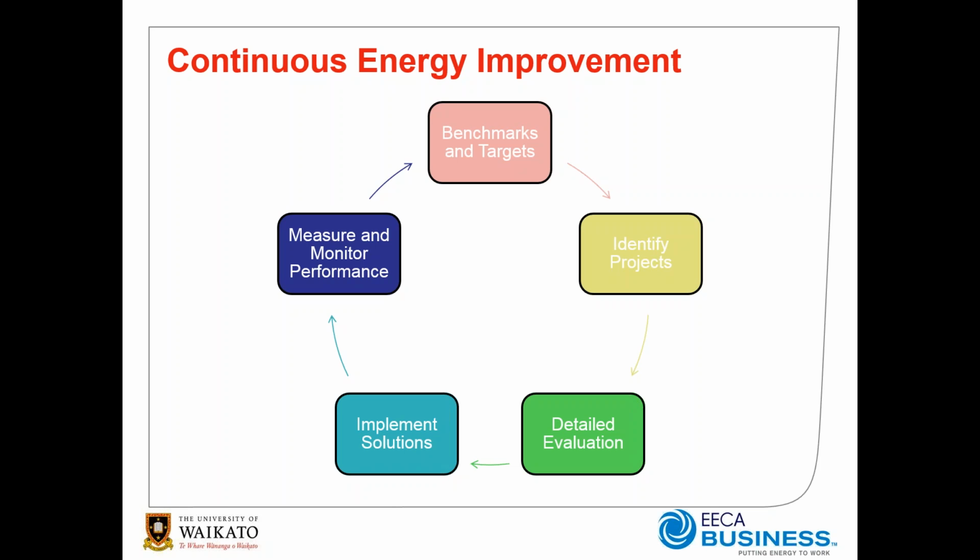It may also include a process simulation of the changes in order to predict what the energy benefits are going to be, as opposed to just an approximation. And then thirdly, it may include some sort of systems optimization where you change both the process operations and the set points of your operations and also the heat exchanger network.